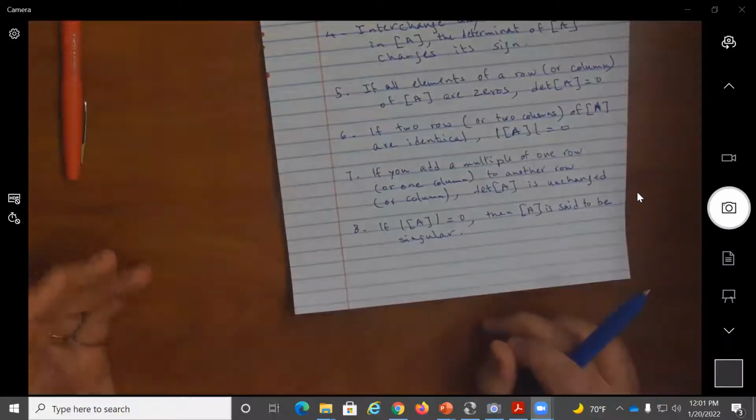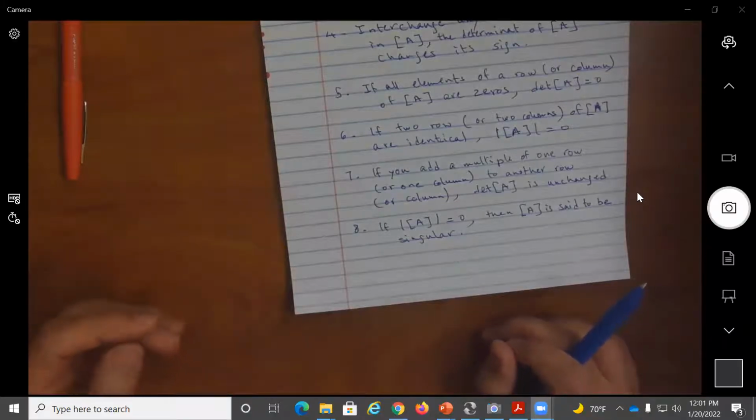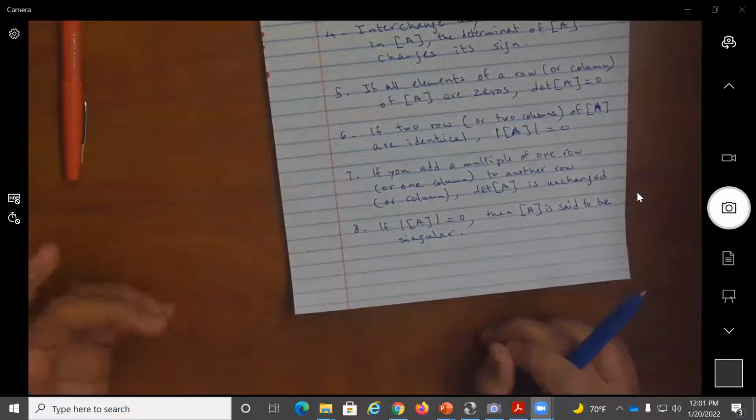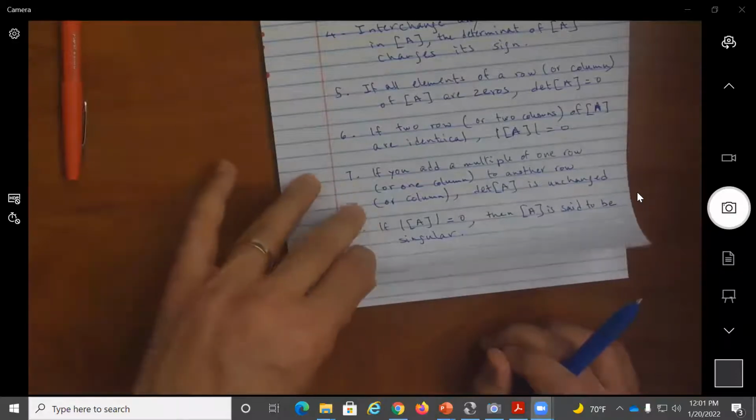When we apply the boundary conditions or the supports condition, then there is a solution. But prior to that, we have no solution, or we have rigid body motion. And that's always one of the cases where when you are trying to run a commercial software package, if you do not have enough support conditions, you may get an error because there is no solution. You run into this rigid body motion scenario.